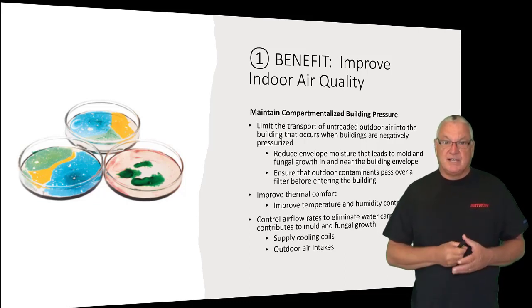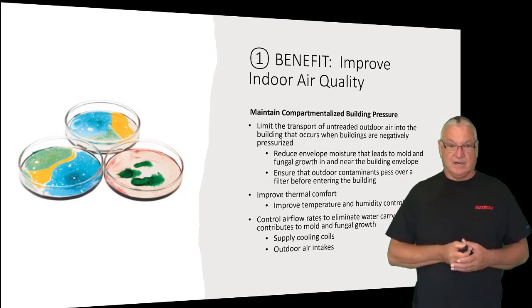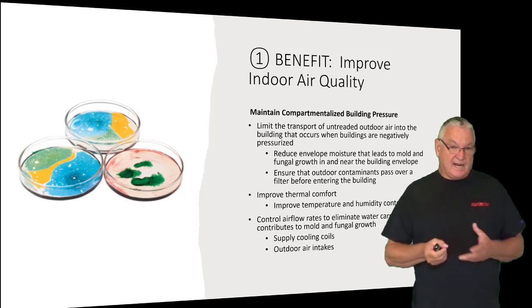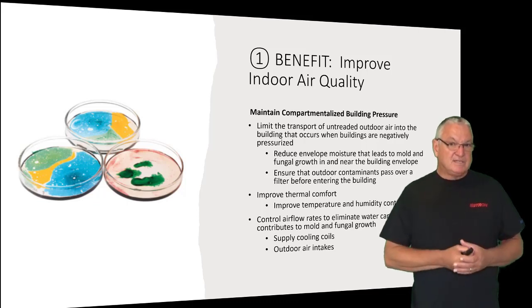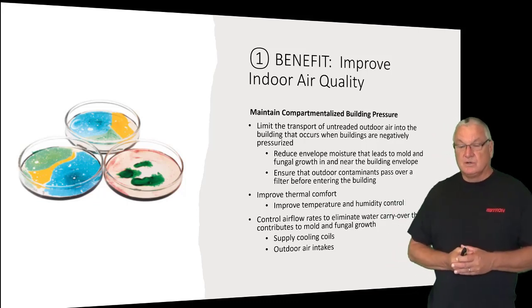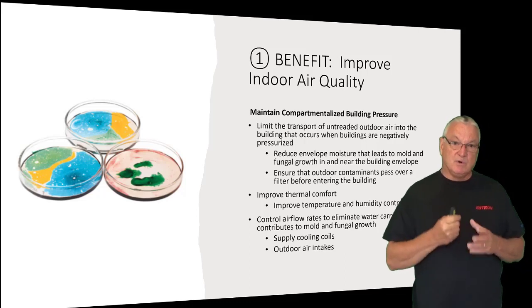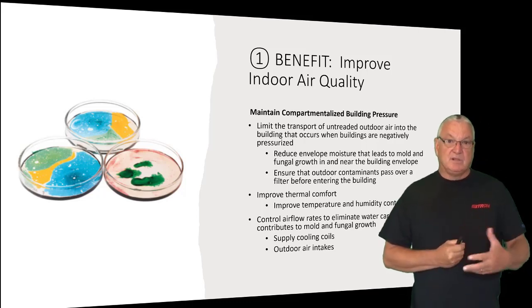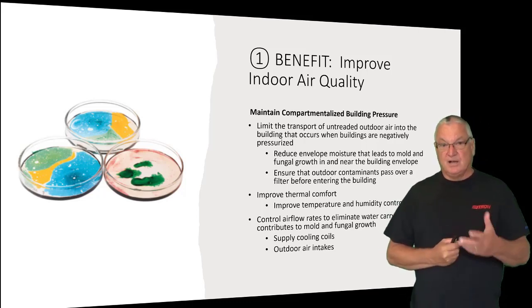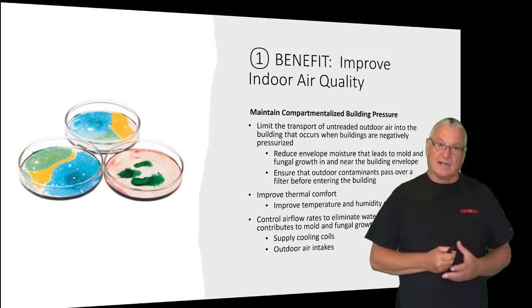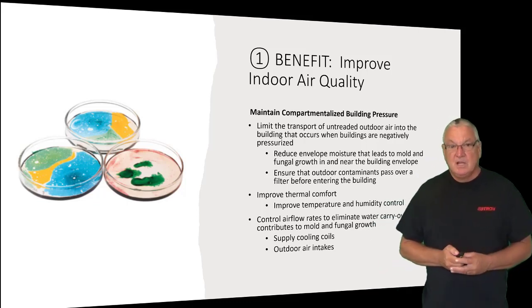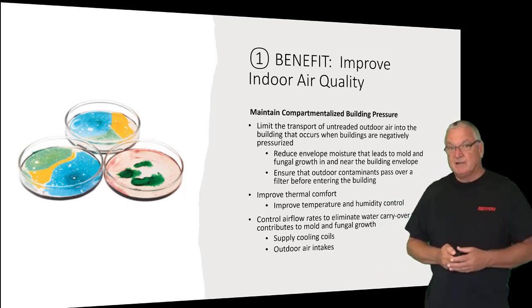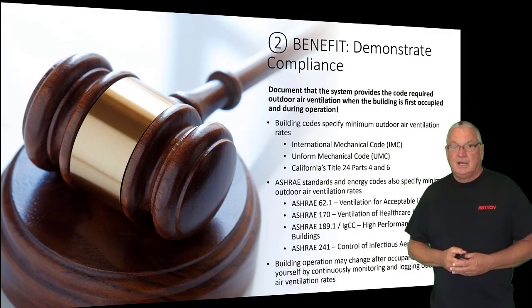In addition to pressurization, you also need to maintain your flow rates because you don't want to bring in too much outdoor air above the water carryover limits of, say, louvers or hoods, because that's going to cause mold problems, as well as supply airflow rates. If you have too high a supply airflow rate, you could have a water carryover, pan carryover problem. So those are things that we would talk about in another presentation.